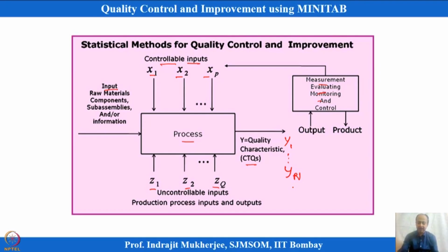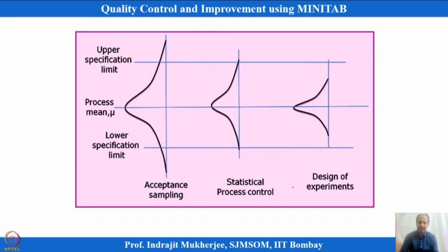Okay. So, if it is a continuous variable and we need to monitor it, then we have a statistical process control approach to do that. I have also shown you a diagram which says that inspection does not do much on reduction of variability or bringing close to target. Assuming everything is on target, we may not be able to reduce variability with inspection, because we are not doing 100% inspection, sometimes sampling inspection.